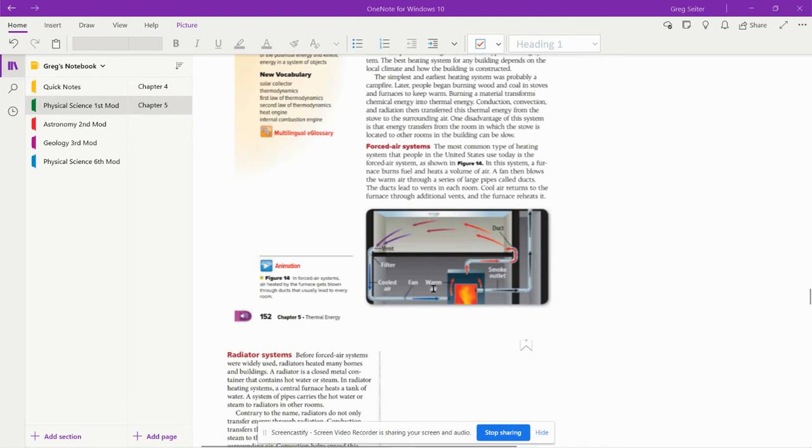In some of the older homes, you may have what was originally gravity heat, or just a convection current in your house. And if you had that, you'll have a great big cold air return on the floor. It's just a vent, but it's huge. I have one in my house that's probably 3 foot by 3 foot, maybe 3 foot by 4 foot. It's pretty big. And that's so the cool air can come back down originally to the gravity furnace, and it was heated, and then it went back out that way.